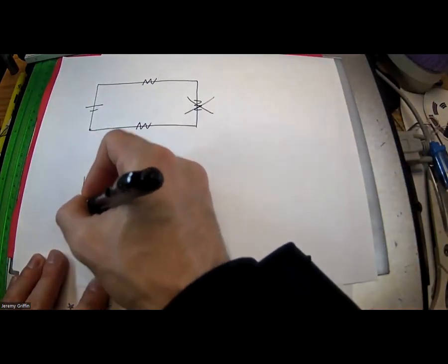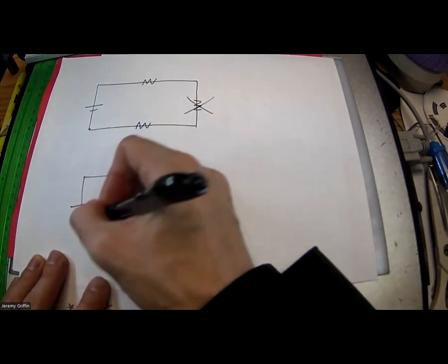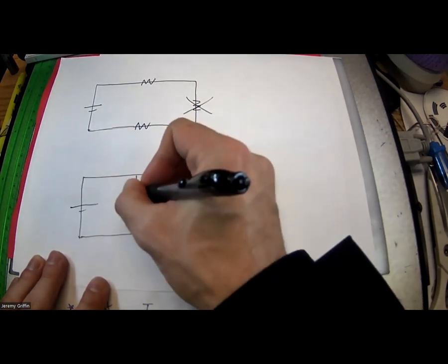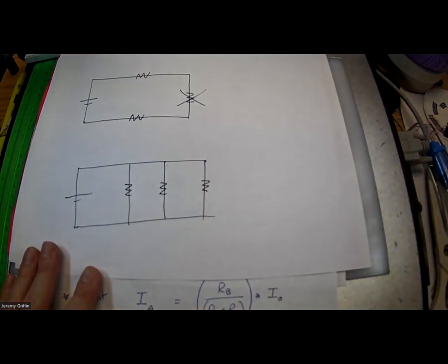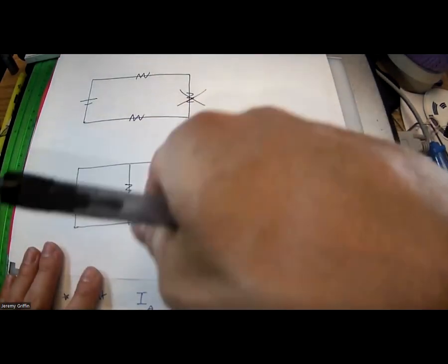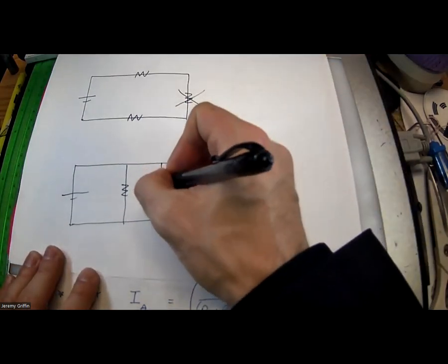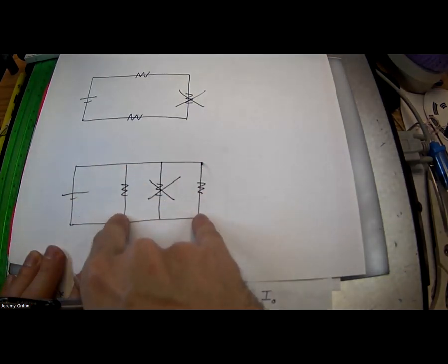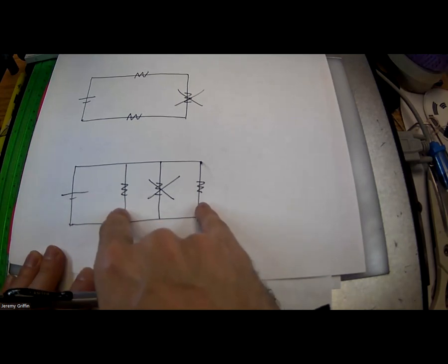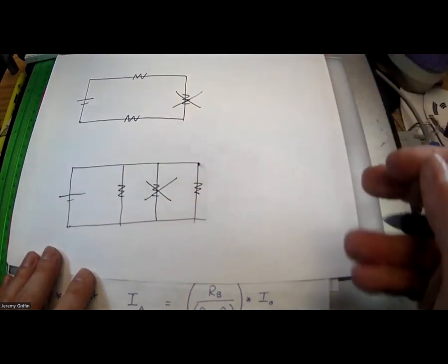Okay. Now, what if you had bulbs in parallel? See what that would look like. That'd be 3 bulbs in parallel, wouldn't it? Right? Now the current has to go through some bulb. There's no short circuit here, but what if this guy burns out? The current could still have a couple of pathways to go through. So wouldn't the other 2 still light up? In fact, their brightness would not change at all, right? Because the voltage difference is the same, resistance is the same, Ohm's law, I equals V over R.